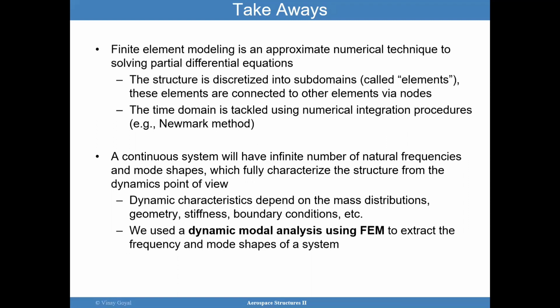These subdomains are simple geometries like triangles, squares or quadrilaterals. We call these subdomains elements. We approximate the partial differential equations over the simple elements and then connect these elements to other elements via nodes. At these nodes is where we solve for the deflections.